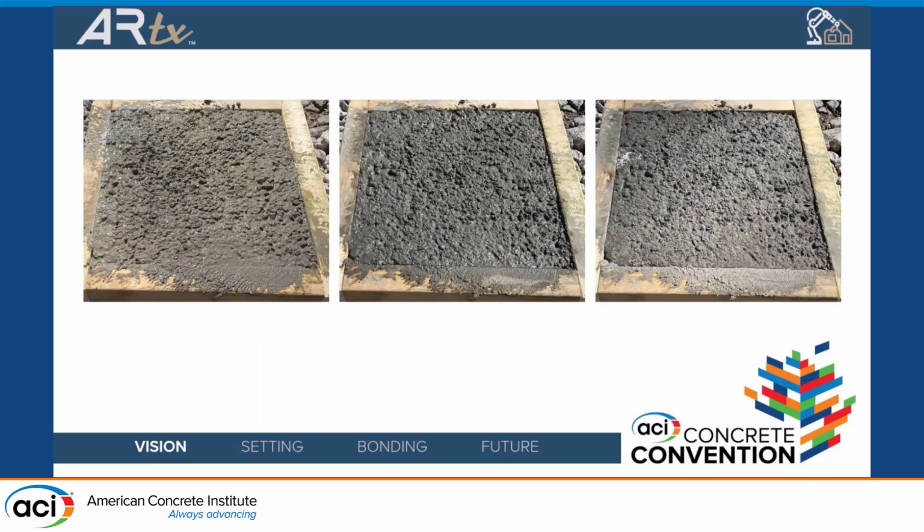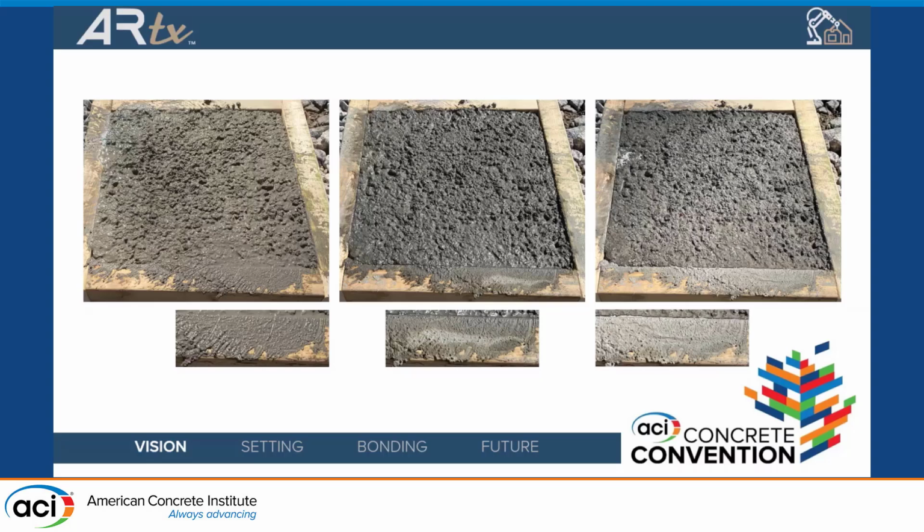In concrete, it can be a little bit more subtle. This is a picture of the same thin section of concrete right after being placed, as it's approaching initial set, and then when it's pretty much set up. At first glance, they look a little bit different. We can see some changes in the way that they reflect light. We can see slight changes in color. If we focus down on this little piece of the concrete that's on the formwork, we can even see that this concrete is definitely set up, and if we needed to do something with it, it's too late.